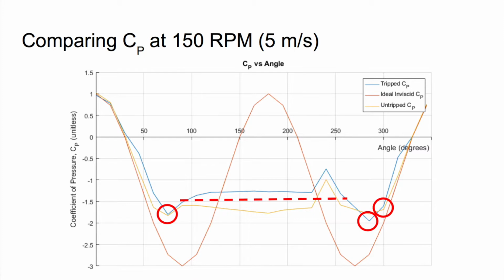Before analysis of the coefficient of pressure charts takes place, the spike at the 235-degree port must be addressed. We believe this spike to be due to an incorrectly calibrated pressure sensor that would often output values inconsistent with the rest of the data we had collected. We believe this to be a calibration issue due to the fact that this offset seems fairly consistent throughout the entire experiment, as shown by the lessening of the magnitude of the peaks compared to the rest of the data, as the RPM of the wind tunnel fan increased.